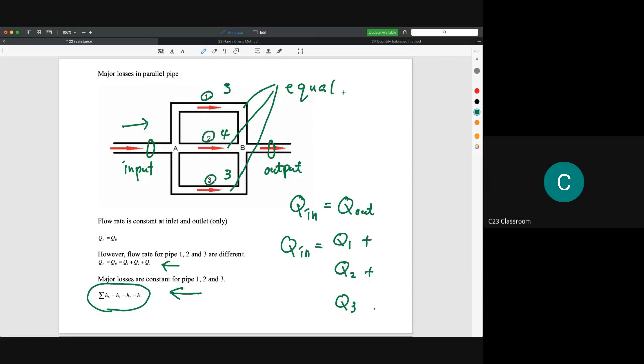It will affect the flow, because the resistance and the losses are quite different. But if you just use three pipes of the same type, inshallah, we could assume that the losses for each pipe are almost the same. That's the idea of the series and the parallel pipe.